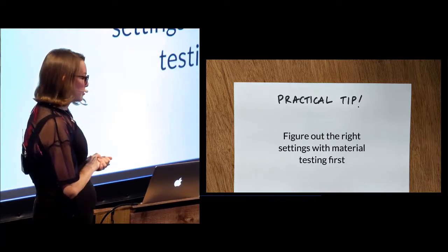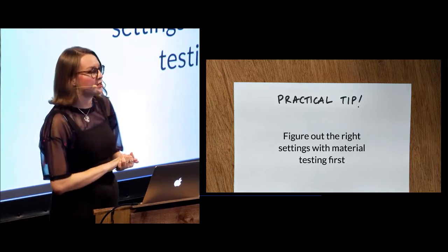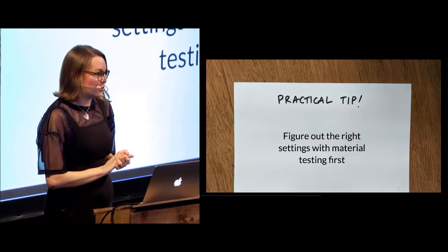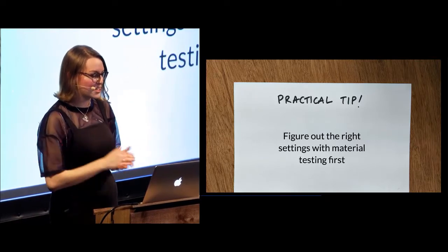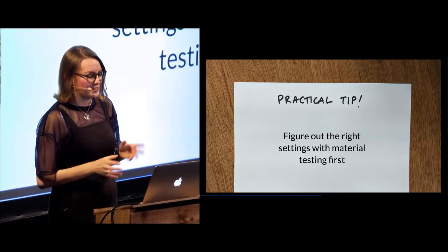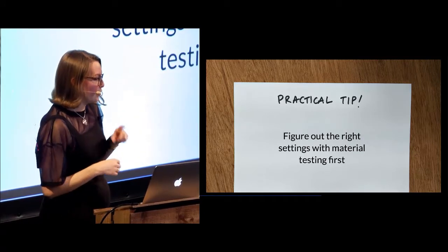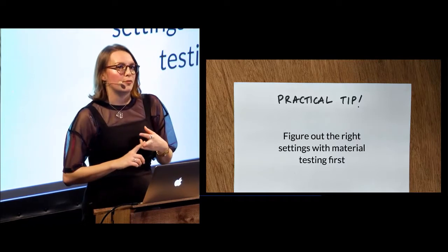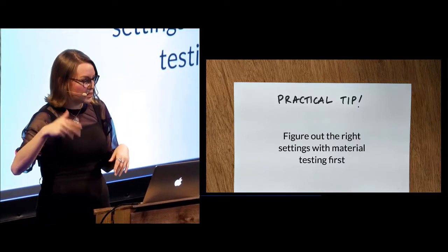My second practical tip is that test-driven development still applies in this context. You may think you can come in with this perfect idea, a wonderful SVG that you've exported, but it probably isn't going to cut the way you'd expect it to. Lasers have both power and speed settings. Usually next to a machine it'll have a list of common materials and what settings they equate to.